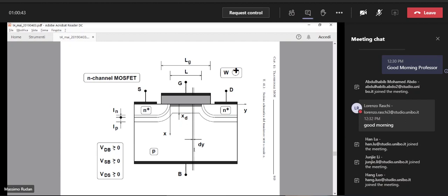In this case, the infinitesimal strip is not actually one-dimensional because when the transistor operates, there is also a lateral current flowing through the elementary strip, in the horizontal direction that corresponds to the y-axis. So it is not really one-dimensional, but almost, as we shall see later. This elementary strip will come of use later on when we develop the analysis of the MOS transistor.